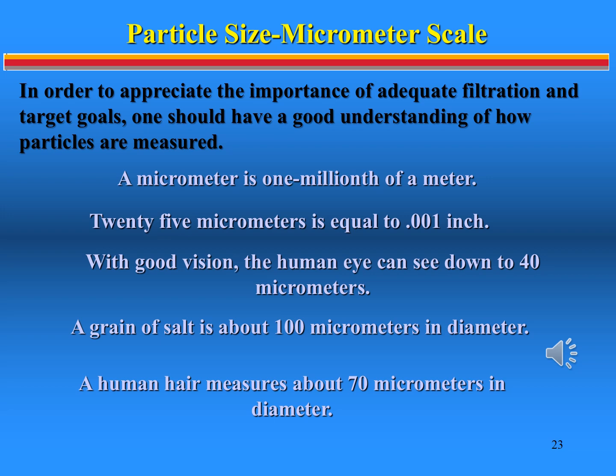may include microscopic analysis and particle counting, already mentioned, using a machine that sends a laser through a sample to measure particles by refraction. To give examples of how small these particles may be, this slide lists comparative sizes of objects on the micron scale. To understand how well a filter can clean oil, you must understand this measurement system and how they're used by different rating systems. Let's first look briefly at filter media.